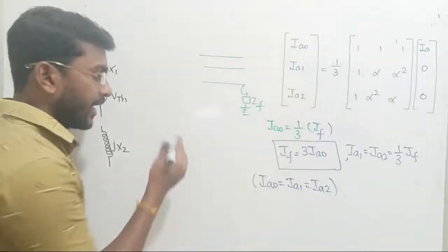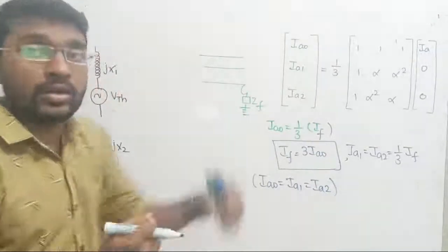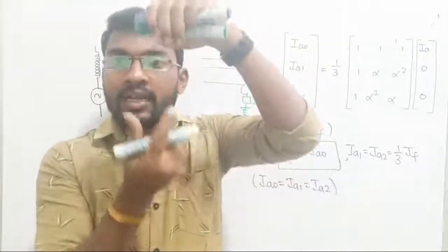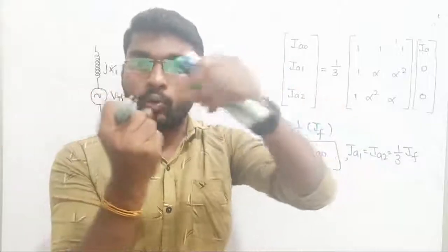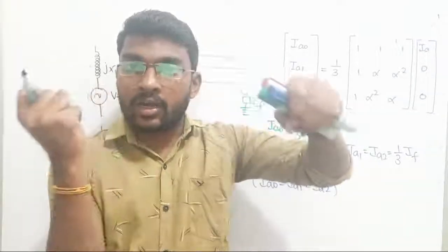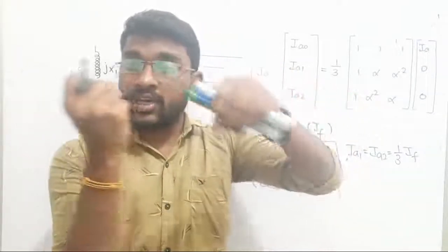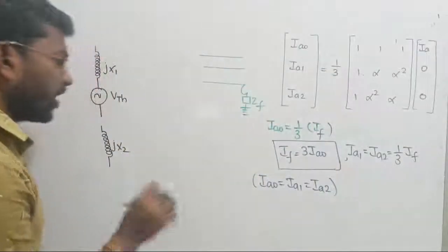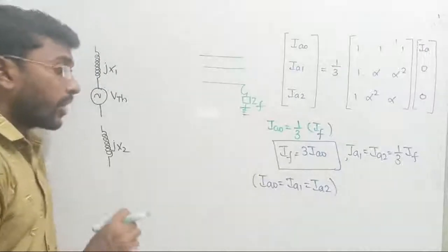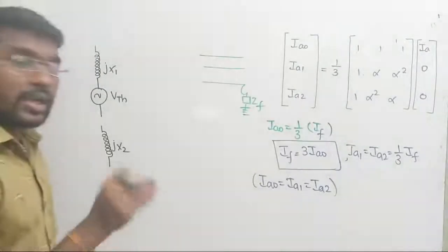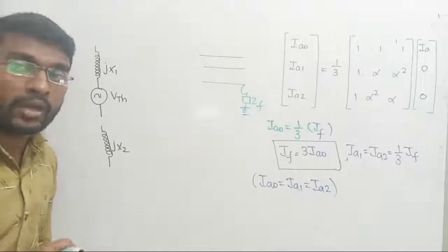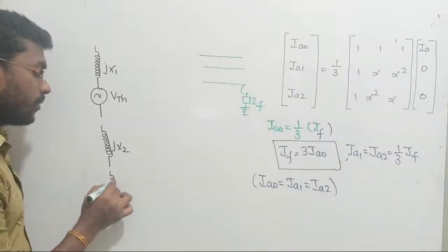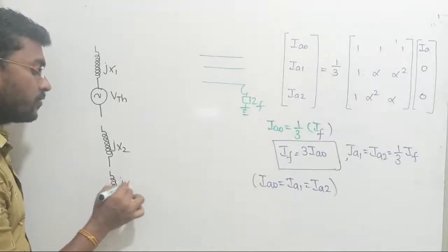Why sir? In negative sequence the rotating magnetic field is going to travel in the opposite direction, such that EMF induction in the conductor is not possible. Why? The rotating magnetic field and the conductor are rotating in opposite directions, so there is no point of getting EMF induction in our machine. I told you already. So in case of negative sequence you can consider the effect of the reactance but you cannot consider the effect of the EMF induction, that will be 0. Similarly when I am looking for zero sequence, I have to consider the effect of jx0.